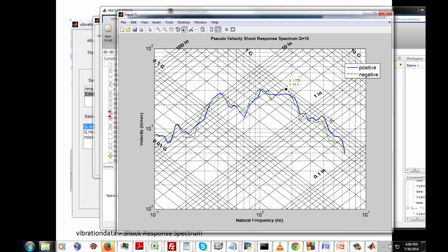But we like to add a safety margin. That's very typical. Or you could call it a statistical uncertainty factor or whatever. So let's add on 6 dB. And if we do that, that's going to double our 1 g level to 2 g's. And then 2 g would be the number that we would pass on to our structural engineer colleagues.